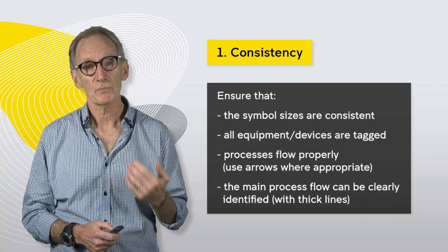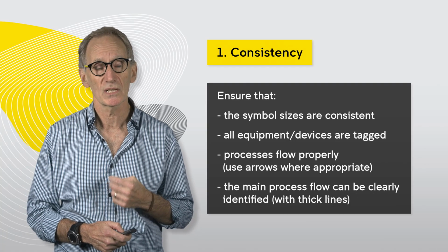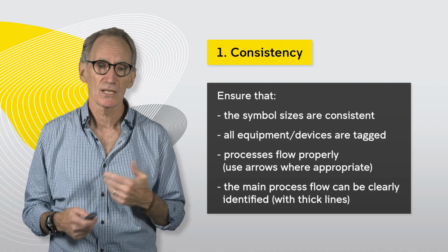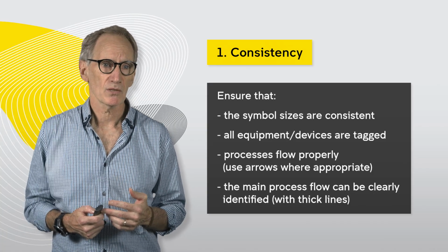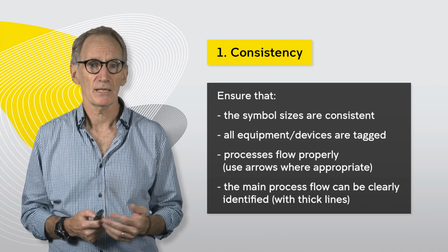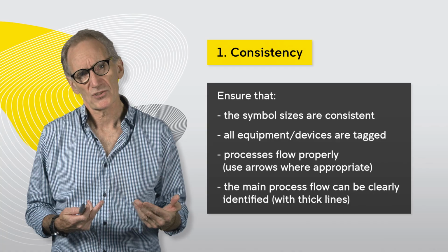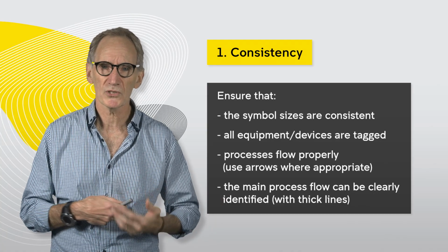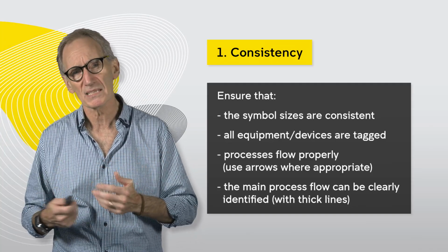You want every P&ID to look exactly the same as far as the symbols that are used, the tagging, the way the flow runs across the page, the presentation of it. And what I often see when I look at P&IDs from people who are perhaps not as experienced in producing them is it doesn't look very professional because they're really inconsistent. I see different size symbols on one drawing to another. The tags don't flow. There's missing tags, missing information.